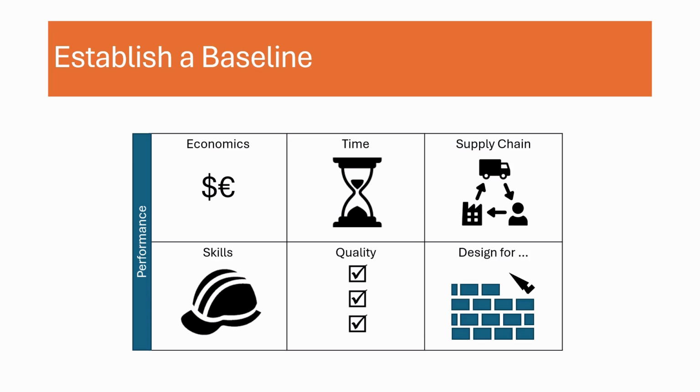We'll briefly discuss the supply chain associated with the materials. We cannot ignore the skills that are necessary. It's wonderful that for all intents and purposes the manufacturing has been democratized, but not for every additive manufacturing process. And if we are doing significant post-processing that requires setup and machining, then we need to have the skill sets associated with people that are familiar with computer-aided machining and CNC machines.